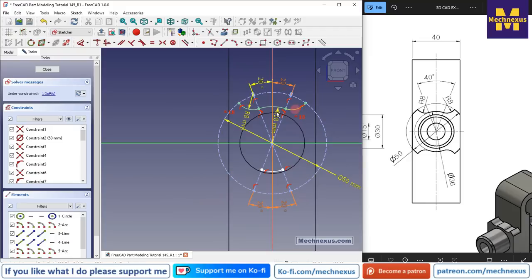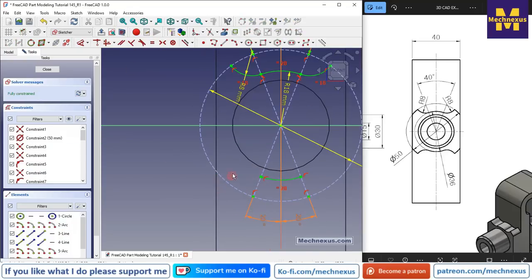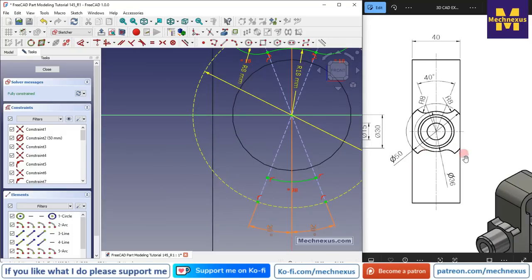If a profile is like a mirror, so here is a mirror profile. So now instead of giving dimensions to this radius, I will simply select both and make them equal. So you can see the constraint, and now we will create these two radii.